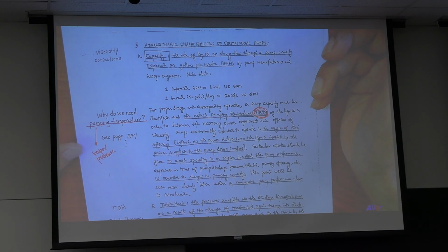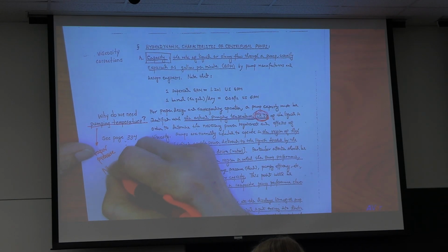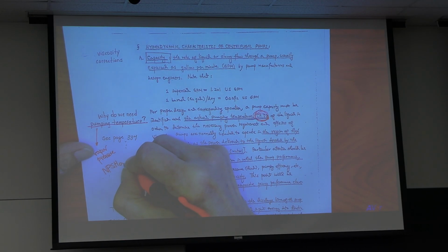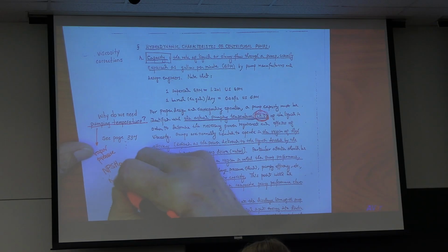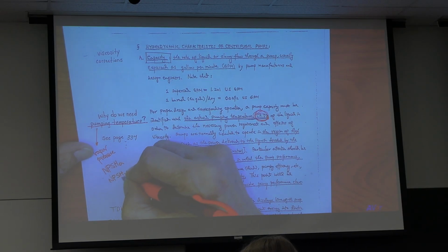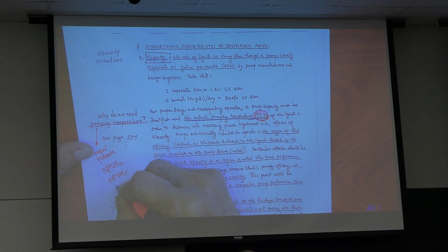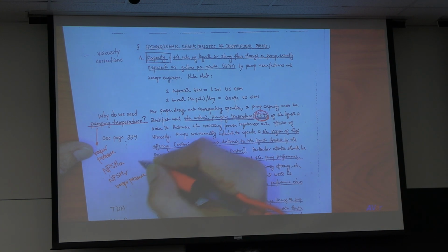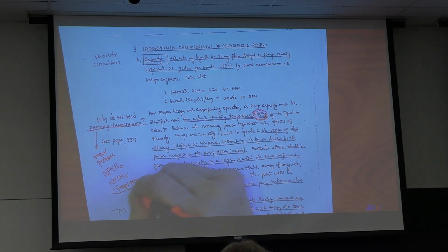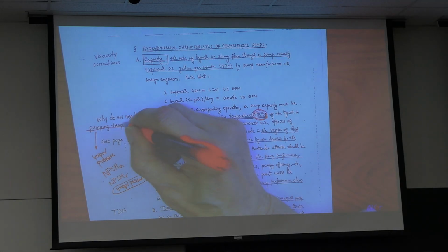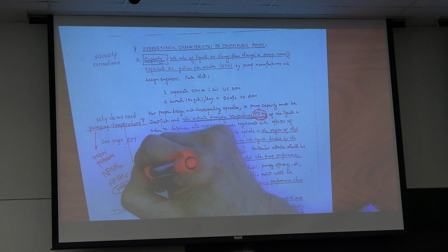Later on, when you find net positive suction head available compared to net positive suction head required, you need vapor pressure. So, vapor pressure is determined by pumping temperature.